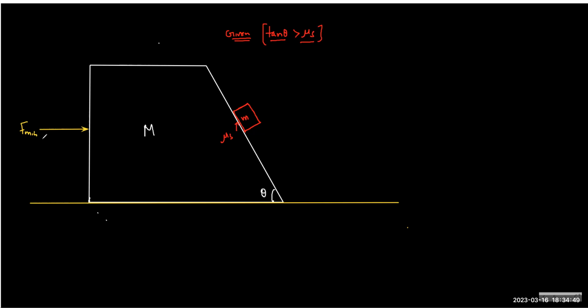So you're writing mg sin theta plus F dash cos theta must be equal to mu mg cos theta minus F dash sin theta, in brackets. Something is wrong here itself. Your FBD you need to recheck actually. The FBD part is not okay, right? Okay, wait, I'll check. I guess there is a sign difference over there.